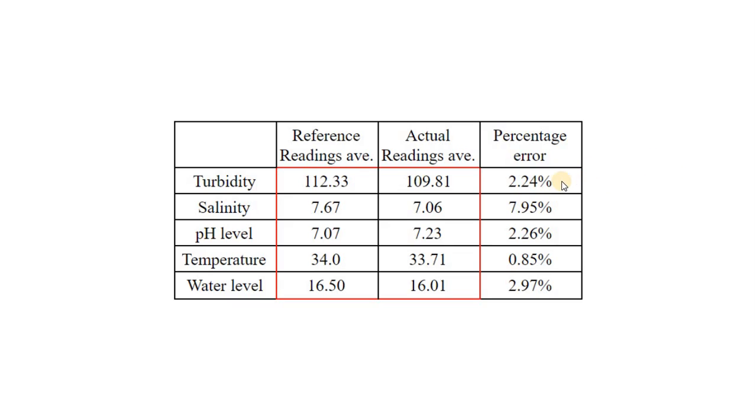One factor that affects the turbidity sensor is how susceptible it is to the change of brightness in its environment, the inconsistency causing irregularities in reading. pH readings are affected by the half-life of the solution that is being sampled over time. The concentration of the solution will decrease, in this case, the coffee and salt mixture. Towards the end of the test, the acidity of the mixture slightly neutralized, hence the average pH level reading taken by the sensor is slightly higher.